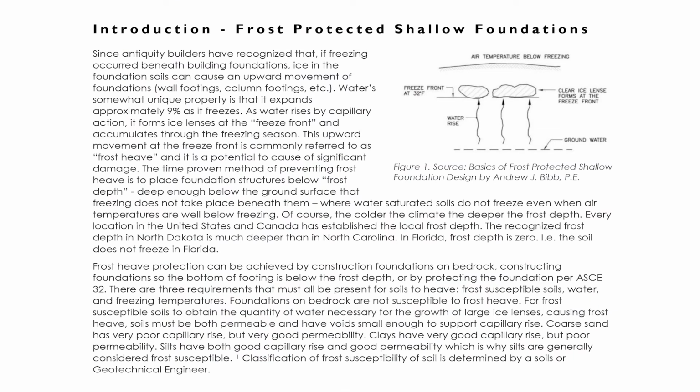And it goes through how the frost can heave up the foundations like we just previously discussed. So the time-proven method is to place the foundation structures deep enough below the ground surface so that freezing can't take place beneath them, similar to the practice of placing water pipes deep enough in the ground so water doesn't freeze them. It's also been recognized that in heated buildings, there's heat loss through the floor construction like we just discussed, and to some extent to the foundation material, usually the soil below the structures, and there's also passage of heat from beneath the structure to the ground surface during cold weather.